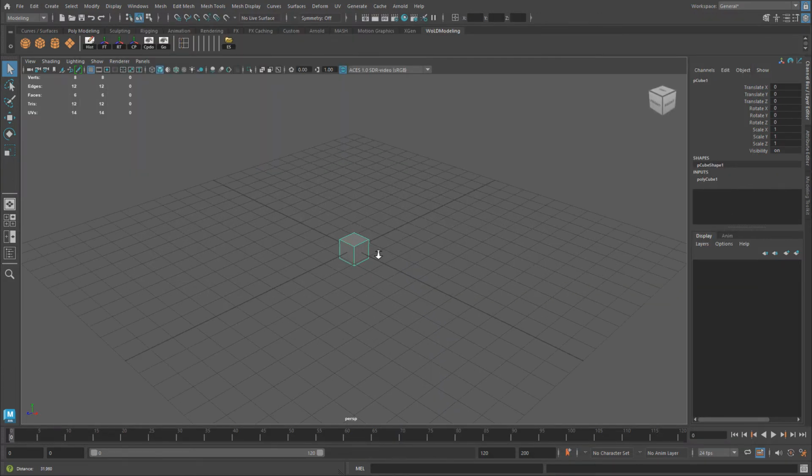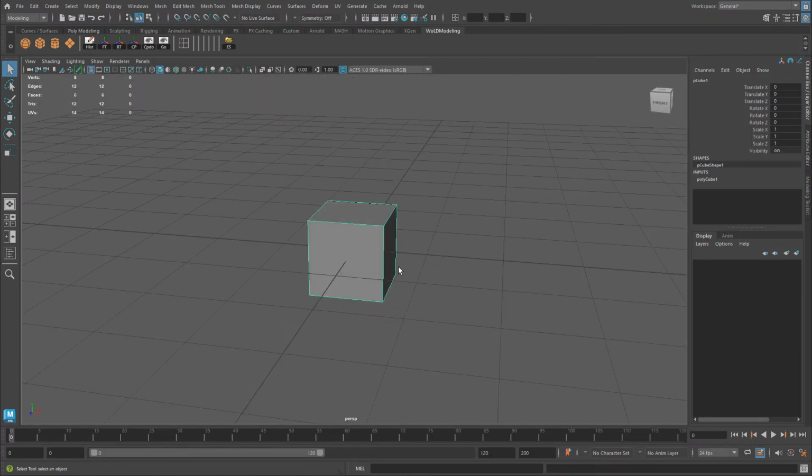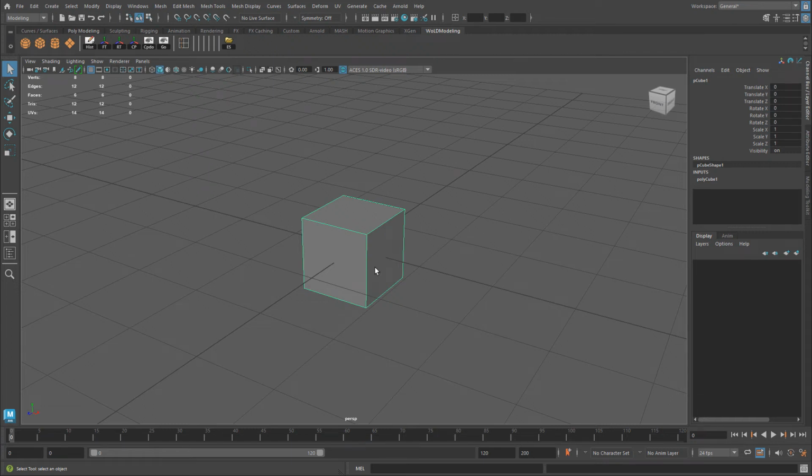And if you are to continue modeling from the default shape, then whatever you create is not going to match the real world scale of an object, unless the object is actually this size. But a lot of beginners begin to model from this cube only to realize that their prop or their environment is incredibly small, and now they need to scale everything up. So everything you model needs to match the real world scale and dimensions of an actual object.